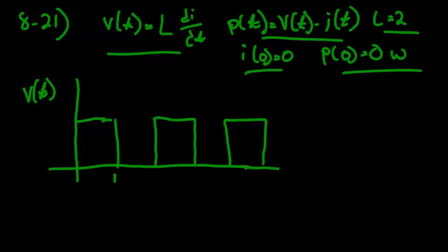So we go from 0 to 1, this is 2, this is 3, 4, and 5. And this value is 6. So at every 1 second interval, we have a switch. We pretty much have a square pulse wave right now. So it's going off and on. It's like turning a light off and on every second. So we have an amplitude. It's pretty much a switch. Unless you have it in a circuit with a capacitance, then this may look a little curved because the capacitor needs to charge up. So there's going to be some time delay to it.